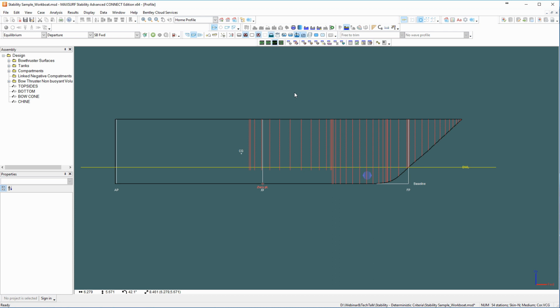In an added weight scenario, fluid flows into the hull and increases the displacement of the ship. In both scenarios, the ship will sink by the same amount. The finished outcome is the same, and if you account for the free surface moments, both methods will give the exact same righting moment. The difference between the two methods is that if you then divide that righting moment by the displacement to get the GZ, then the added weight method, with a larger displacement, will give you a lower GZ than the lost buoyancy method.